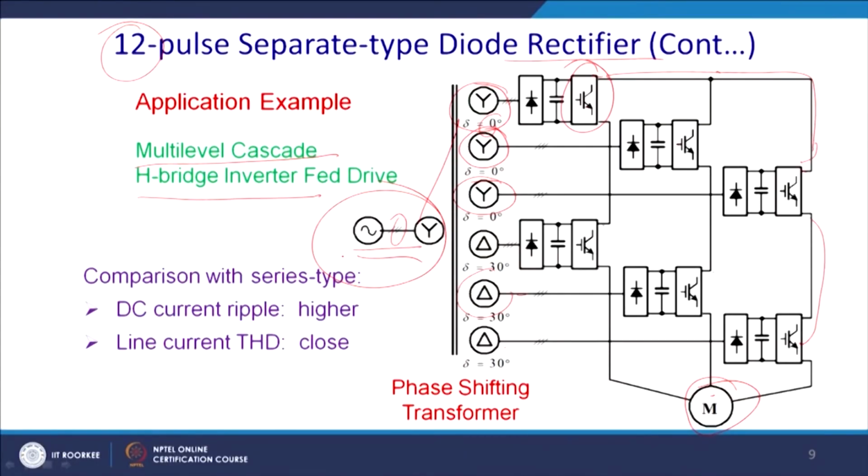Apart from that, you are not using a special kind of transformer, because if you want an 18° phase shift, or a 20° phase shift, then you require special construction for it, and thus it requires customization in drives. If you do customization, like if you take a shirt which is not commercially available, you require to pay more.